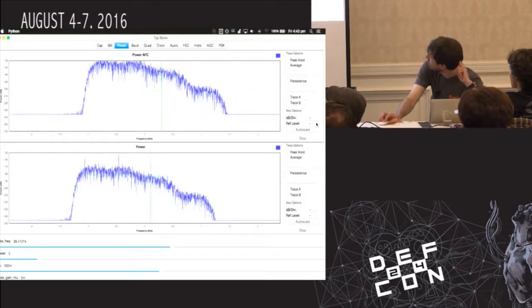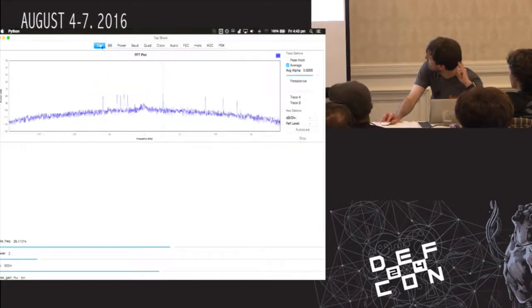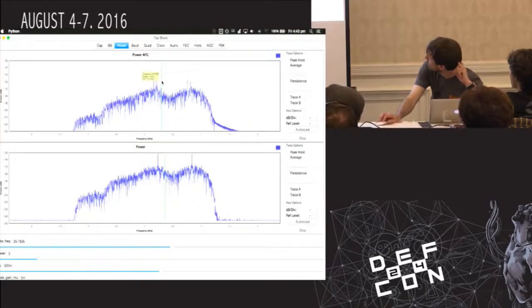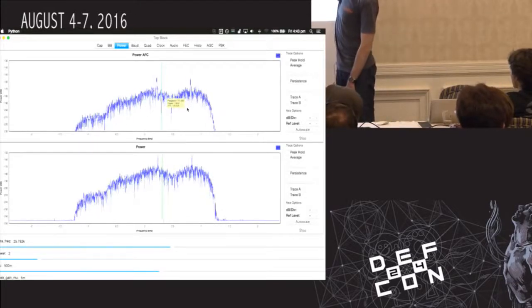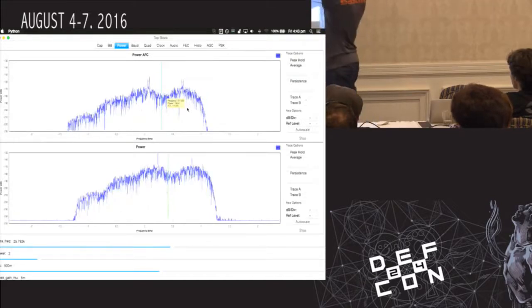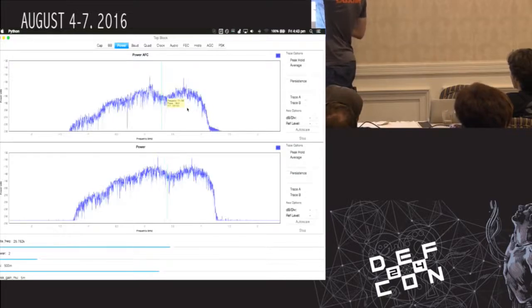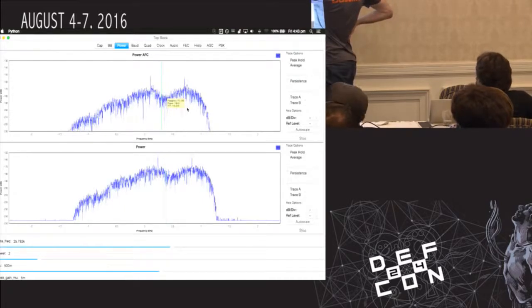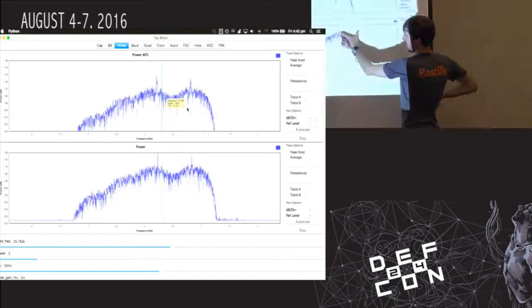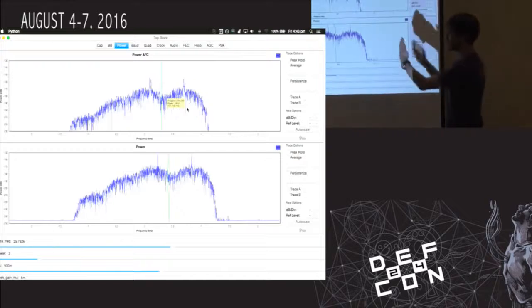In this case, I was using that squaring technique with the peaks. See, even that should get it. The newer version does get it, but that's still slightly off. So what this is doing is it takes the output of this FFT, and then it looks in one half for the highest peak, and then uses that to calculate the frequency offset, because this peak should be at 300. It should be at half the symbol rate out from the middle. And so whatever the difference is between that expected peak and where the actual peak is, that's how much it'll shift the frequency over automatically.